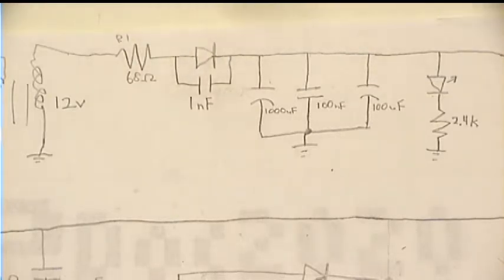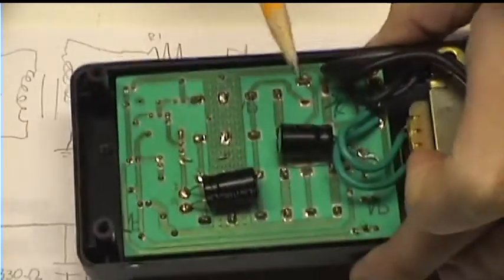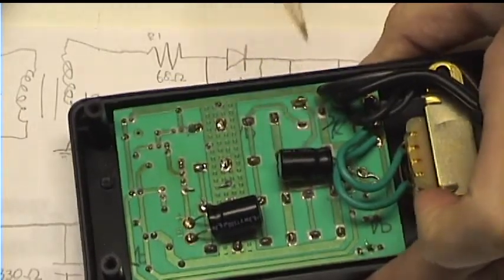I would have preferred to see a full bridge rectifier, but this still works. So then the rectified AC signal feeds into some filter capacitors. You have a large 1000 microfarad capacitor. That's this one on the board.